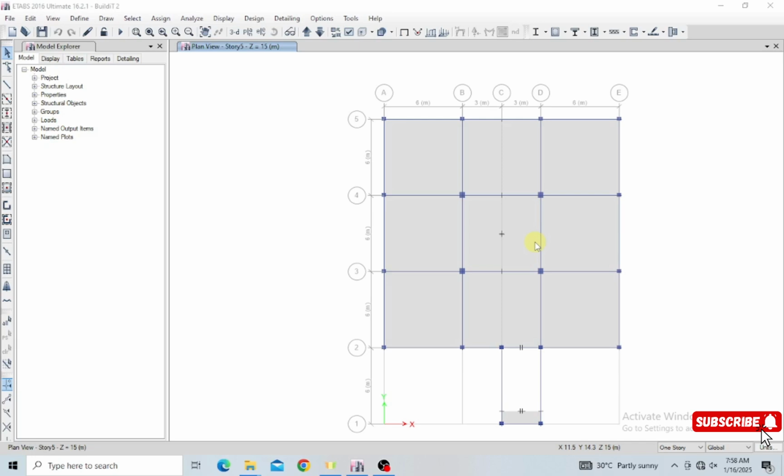So these shear walls, as I said earlier, are wall-like structures, and we are going to draw our shear walls in our structure. Typically, most of the time our shear walls are located where the elevator is. When you have an elevator in your structure, the shear wall is mostly around that elevator. So basically you don't really see that there's a shear wall there, but sometimes there is. Some people also put it at the exterior side, as peripheral walls outside here. Where you place your shear walls is all up to you.